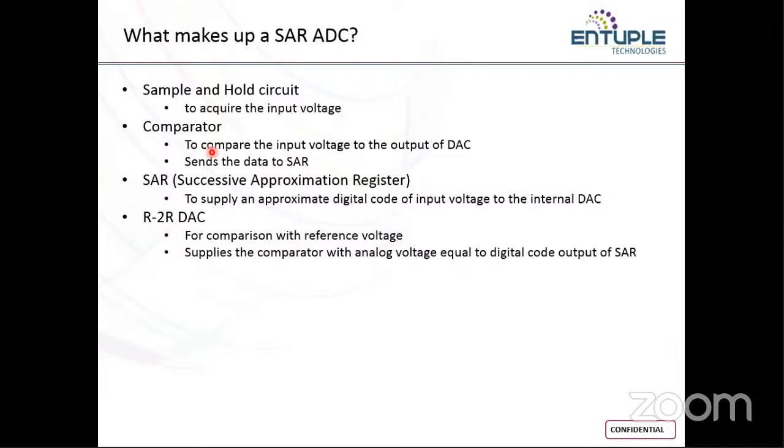That value of voltage is going to be reformed. You are going to reconstruct the signal using that particular value of voltage. So there are chances of missing certain values, and that is what we call quantization error. We have a number of options in order to remove that quantization error, but that is not the block which we are concentrating on here.